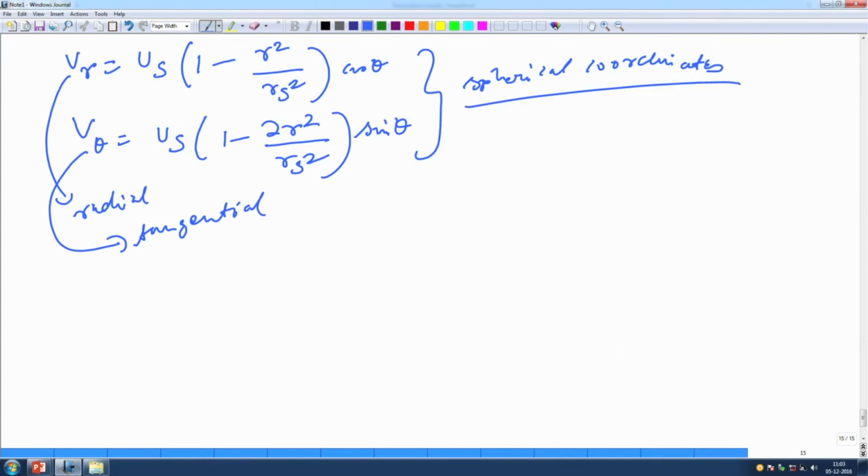We also assume that these velocities are, by the way, variable, okay, they are not constant, but we assume that the Hill spherical vortex applies to the unsteady situation also, during the vaporization of the droplet. The simple reason is that we already established that the vorticity transport happens in a much shorter time, and that is the reason why we can actually go by it.